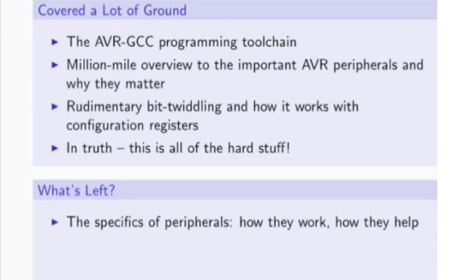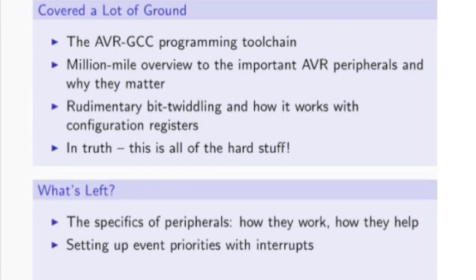The timers can count so fast that you can make an AM radio by toggling one of the pins on and off and then modulating sound over that. You can play back sampled audio by running these things fast enough. This is all stuff that you can do only if you have access to the configuration registers and know how to use them. So you could push these peripherals to their limit, and I personally think it's super fun to do that once you know how they work.